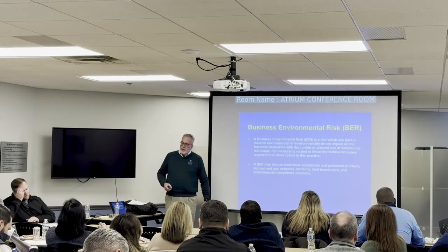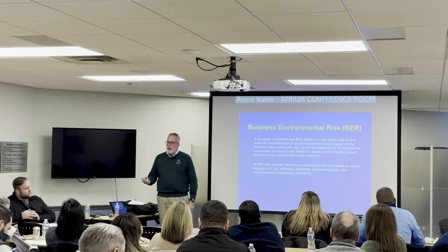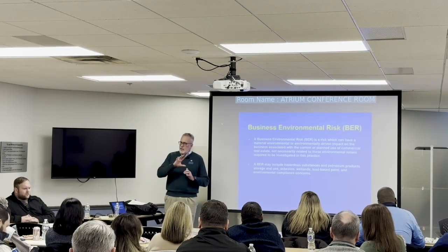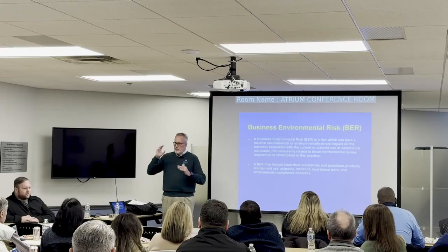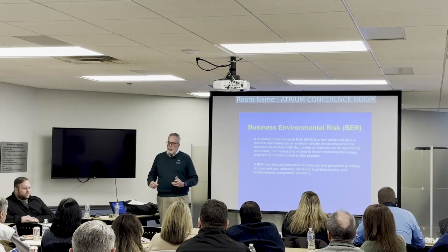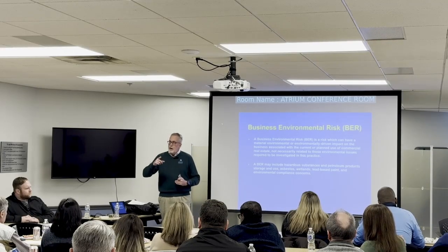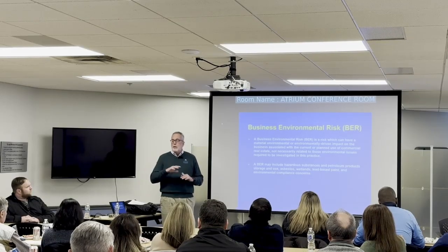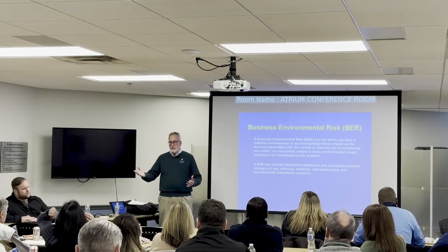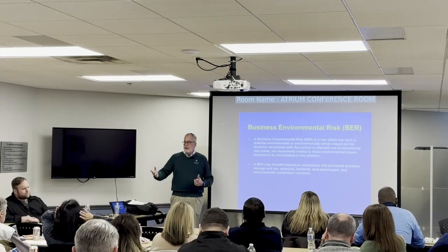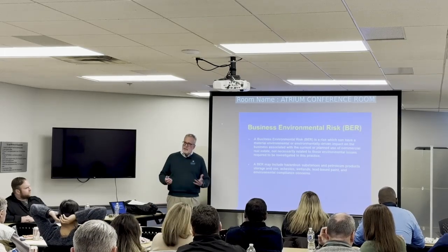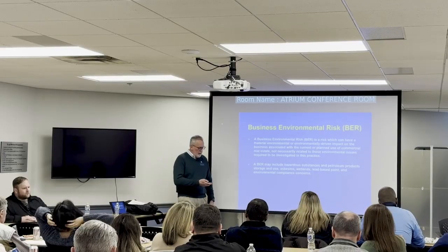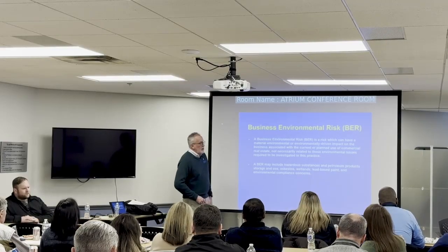And then we use the vapor intrusion screening levels calculator, so we can put all the chemicals in, and it does all the math for us as far as cumulative risk. We can set that at 1 in a million or 1 in 100,000. And also the hazard quotient, you can use a 0.1 or a 1. We use a 1. 0.1 would obviously be 10 times more conservative, and I think that's more on some of these hazardous waste sites. Under RCRA, they use some more conservative risk scenarios.